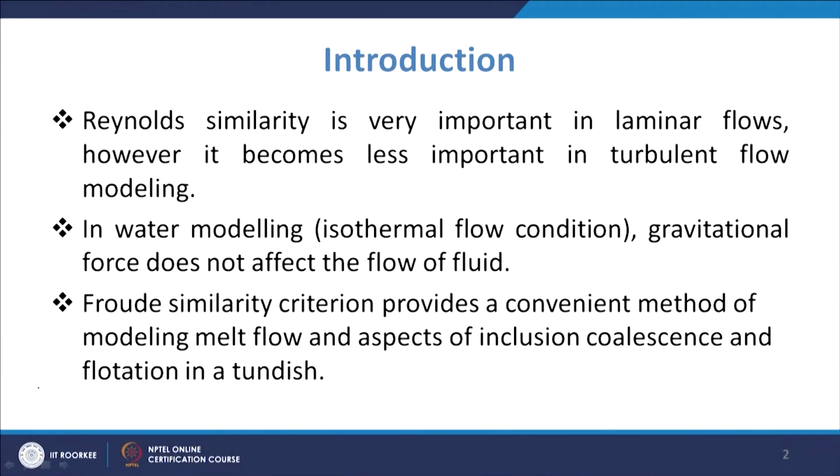So, Reynolds similarity will be important in laminar flows. However, it becomes less important when there is turbulence. Also, in water modeling, when we do the isothermal flow conditions, the three forces which are mainly there are inertial, gravitational and viscous forces.